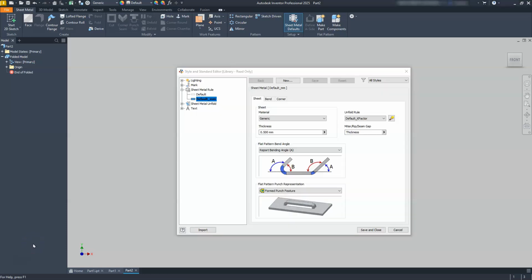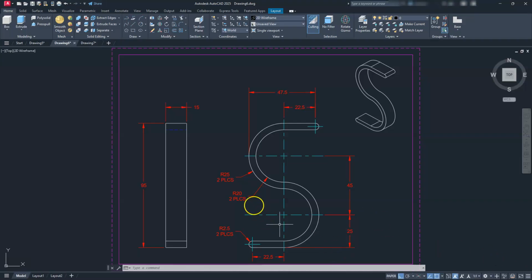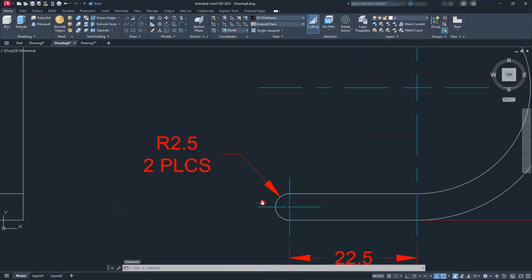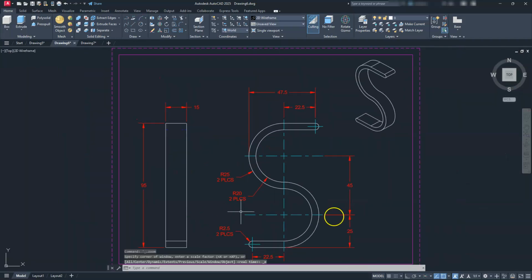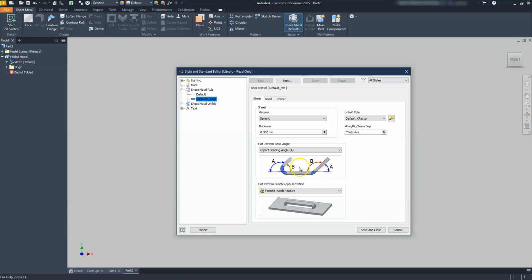When it does, you should see something that looks like this. We have the thickness here, so I can physically change the thickness here. Back on our drawing, if you remember, the thickness here is going to be 5. We see that from this 2.5, and we're just going to wind up doubling that number. So the thickness that I'm going to use here in Inventor will be 5. Since I'm using the ISO of millimeters, it's going to assume that I'm using 5 millimeters.